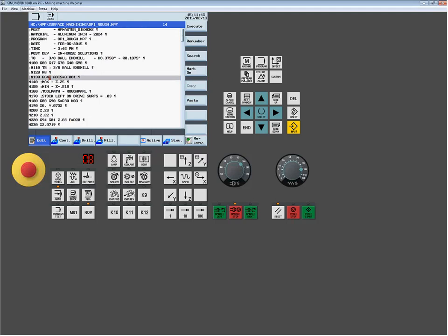Whether I want the spindle and feeds is really up to you. I'm not that concerned because I'm passing them through with R variables. But you don't want operators to have to go into the subs to make any editing changes. The only area they should go into, if any of them, would be certainly in the main program file. So I just commented out these lines. If this was a real part that I was going to do in production, I would just delete them. No need to see this kind of stuff.